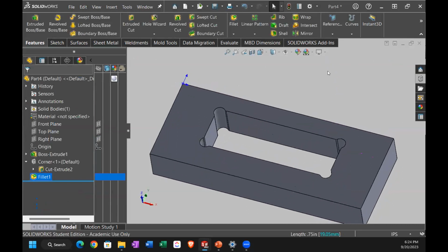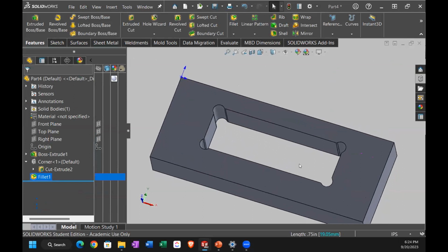So when I put this into the CAM package now, and the tool is done pocketing this out, and I go to finish this surface, bringing the geometry into the size and the shape, when it gets to this point, it won't be a hard turn, or if this was a circle right on the corner, the tool wouldn't go in there anyway.